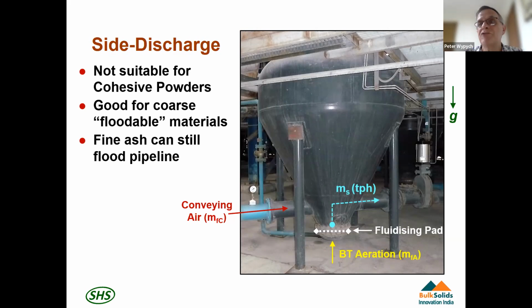So if you imagine dropping fine fluidized ash from above, the ash is aerated and it's hot, and it dumps into the tank, it can run out into the pipeline to some distance out to the outlet valve, no problem. So you could start off with a full block of ash in your pipeline before you turn the conveying air on, and that could cause some problems too. So we've got to watch that. But the amount of lift here is very small, so your feed pipe losses are minimized.